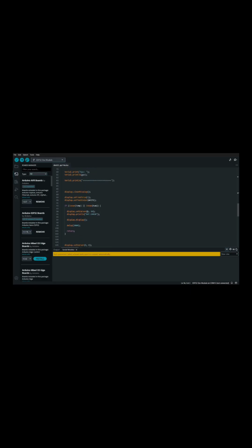Then display.clearDisplay, so we have called the function again here. Then we set the text size and text color. We have also given the condition: if temperature is not a number or humidity is not a number, then set the cursor and display a DHT error if our DHT is not working. Then there is also a 2 second delay for the DHT, so the temperature and humidity update every 2 seconds in real time. Then display.setCursor for humidity and temperature, setting where each will display on the screen.